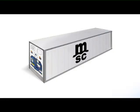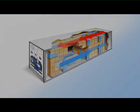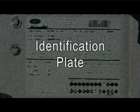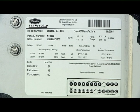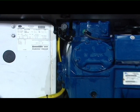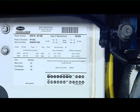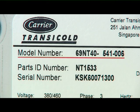The container refrigeration unit is designed to be installed in front of the container and to maintain the cargo at the desired temperature by allowing air to circulate throughout the box. Identification plate. The identification plate is a metal or plastic plate fastened onto the unit's frame located on the left side of the compressor, on which all the information related to the type of the refrigeration unit is mentioned. Model number indicates the engine type and shows which configuration and software has to be loaded into the controller.